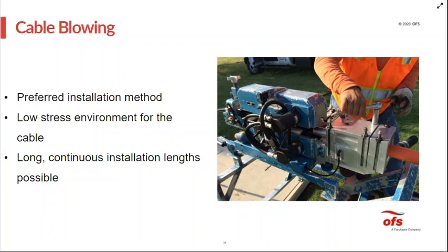Blowing is not impacted as much by bends in the duct as pulling is. Bends have a very, very severe impact on your pulling lengths when you're pulling cable. But there is an impact in blowing, but not nearly as severe.